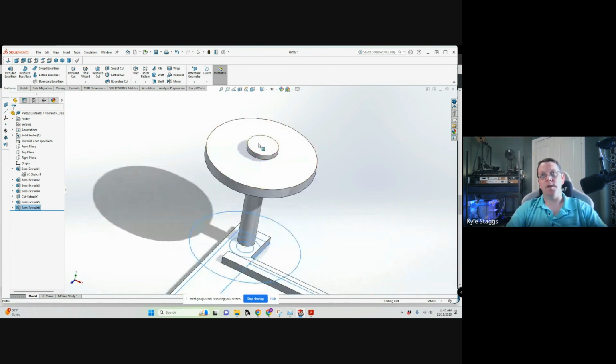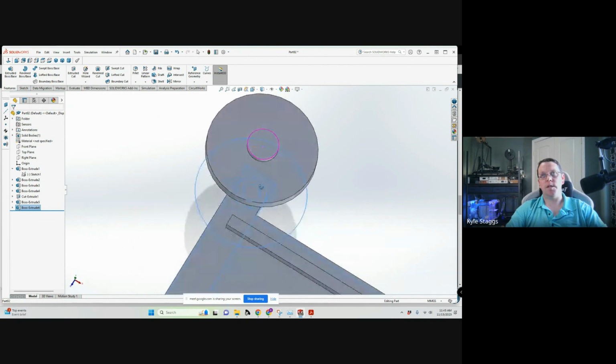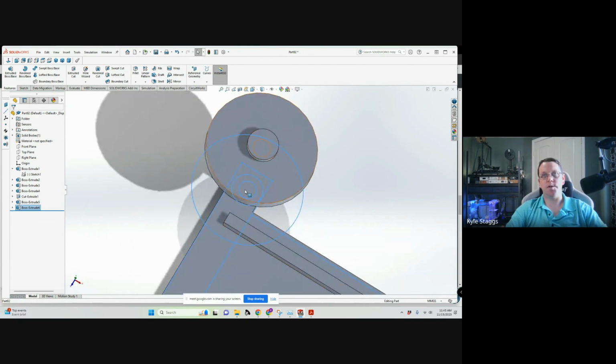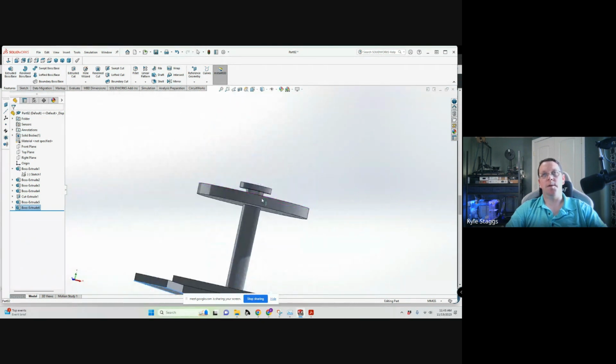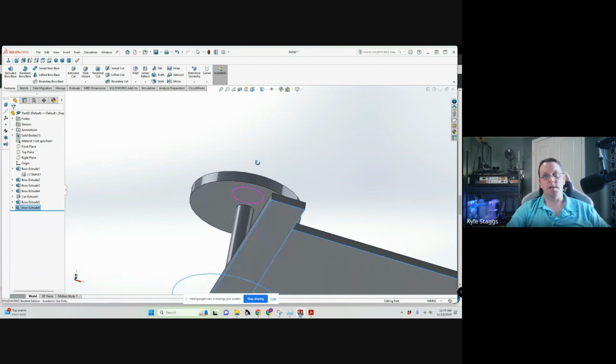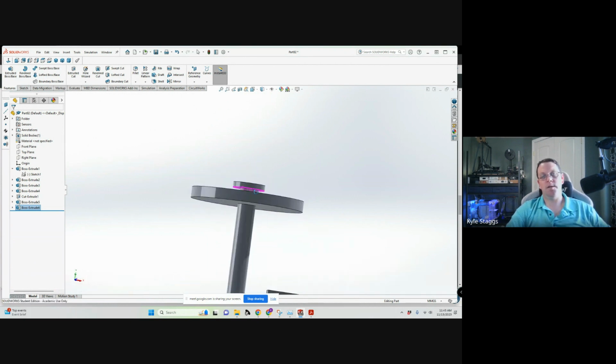And you might need to increase. It's easier not to do tapered holes. It's easier to do an inner concentric circle for this middle part. And then this can work as a print in place roller. If this fails, then you just have the machine shop help you drill a hole, put a screw through, and you're fine. So if the print in place fails, it's no big deal.